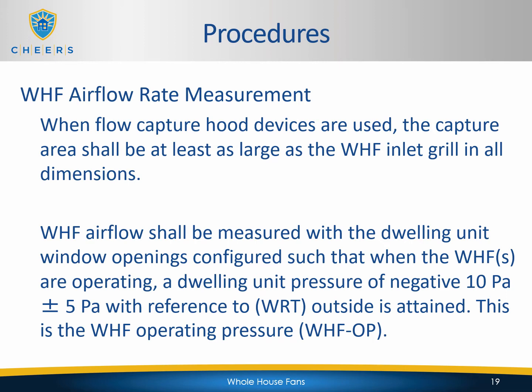If you have the windows closed to where you have a negative pressure of say 20 pascals, you're not going to get as much airflow through the fans. And if you have it to where there's 0 pressure difference, so all the windows and doors are open and the fans are just running, there's going to be more airflow. So you've got to find that balance. The fans are designed to run with the windows partially opened so that it's drawing air into the house and then out through the attic. So this is going to be a standard procedure for all of the tests, is to first set up the house, set the windows to where you get that -10 pascal pressure difference before you do any airflow measurements.